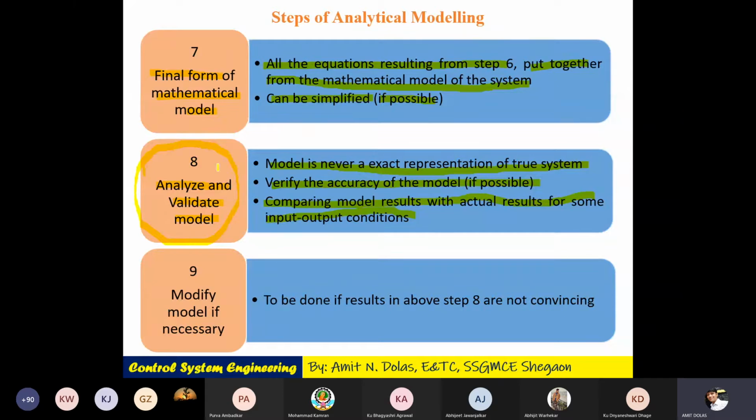If it is open loop, what will happen? We turn on the AC, it will maintain a certain room temperature. Then it is not under control. If some disturbance is there, like a few people coming into the room, the temperature will increase. But as it is open loop, it will not be understood by the system.